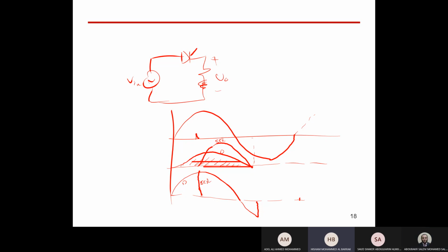Can we say that at the end the VRMS of the diode is higher than the VRMS of the thyristor? Yes, sure. For this circuit, it has to be like that because diode will pass the full waveform. However, thyristor will control it. So we can say that thyristor and diode can have equal voltage only if the thyristor firing angle is 0, which means you fire at this instant.